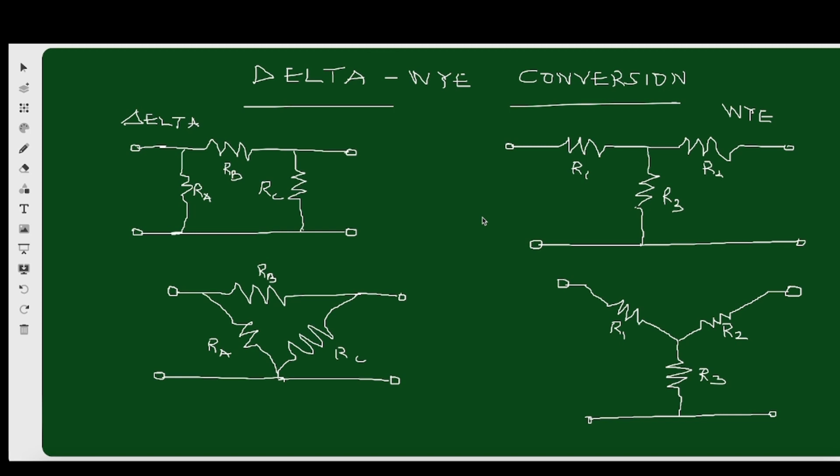So imagine we are given a very big network of resistors, right? Where you discover that there's a particular delta connection between three resistors, and if you connect it to y, it will make maybe R1 series to another adjacent resistor, or making R2 parallel to another resistor, so that it can simplify your circuit. So that's the purpose of Delta-Wye conversion.